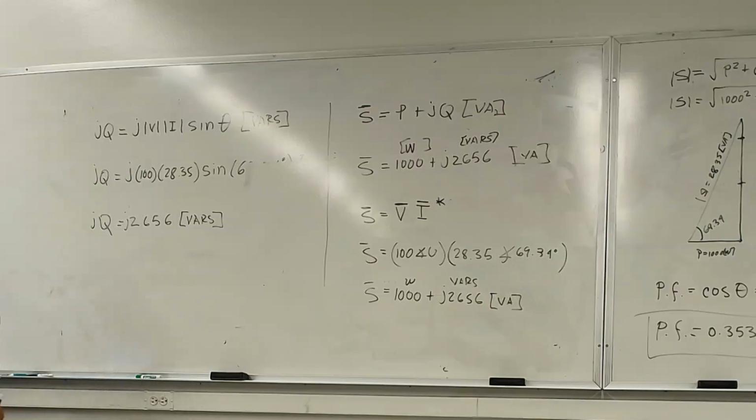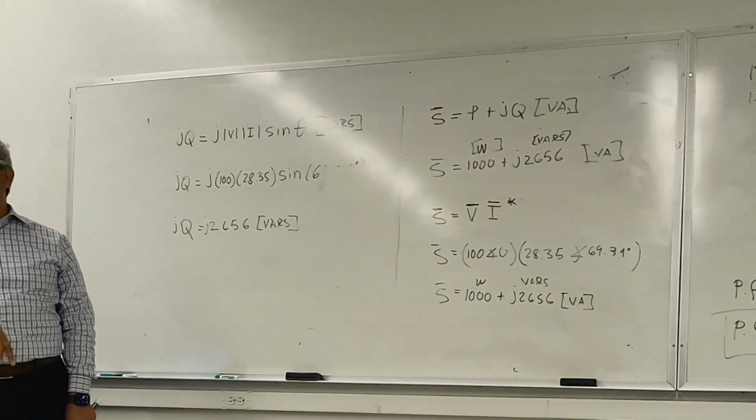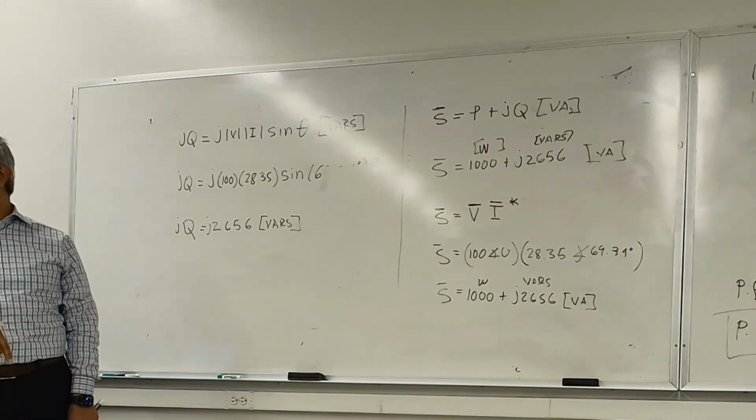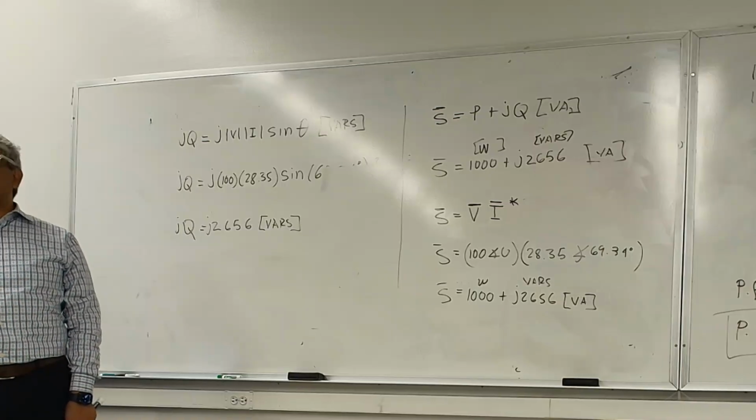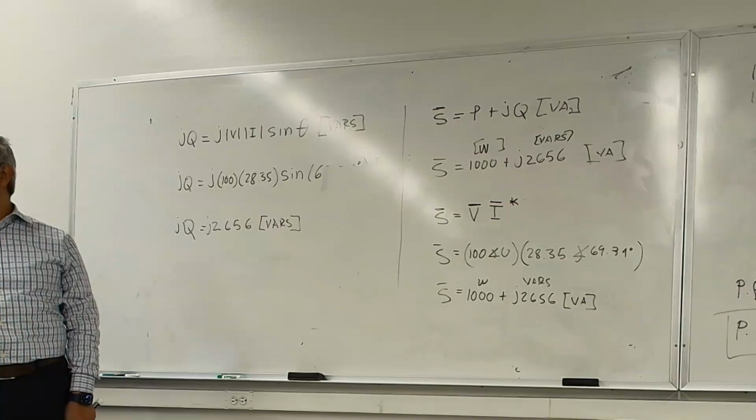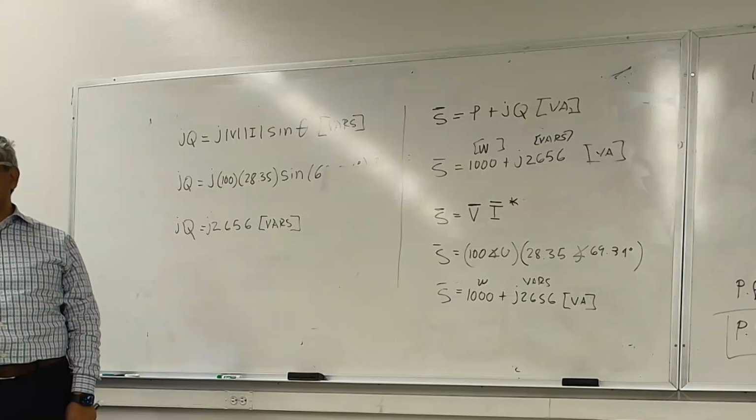So you might say, then why in the heck am I going to use capacitors? Why don't I use synchronous machines? They're more flexible. I can do more things with them. But very expensive. Very expensive. Those are very expensive vars. Capacitors are cheap in comparison, right? But there are a lot of good things about synchronous machines.